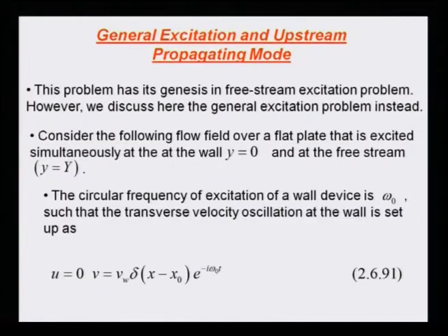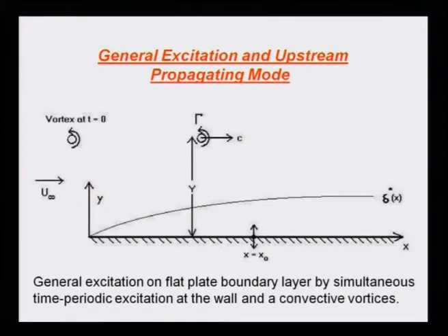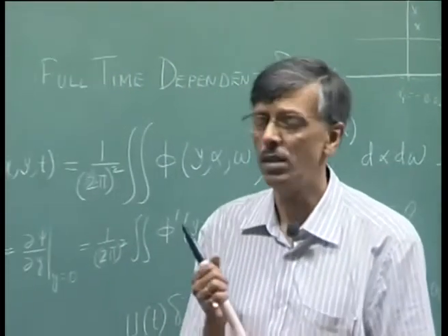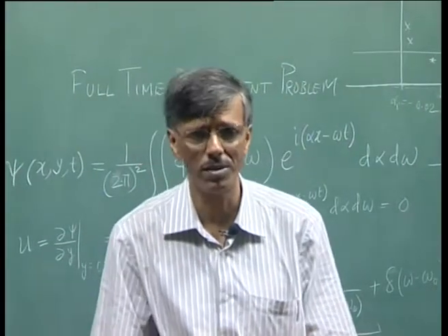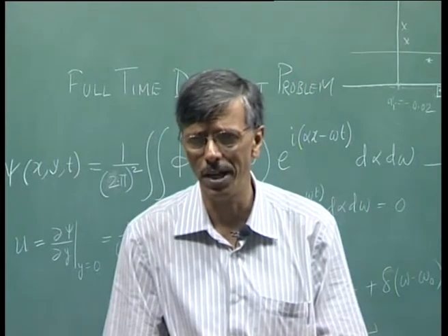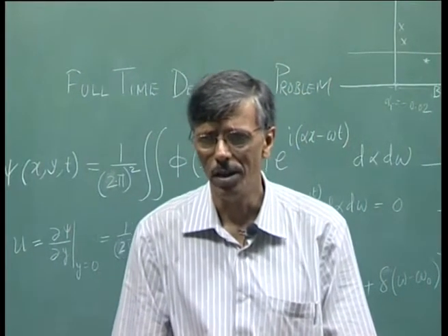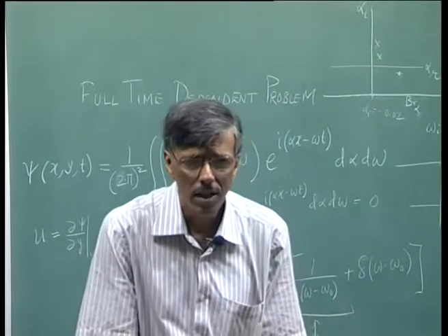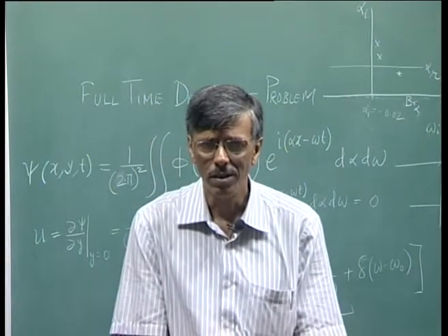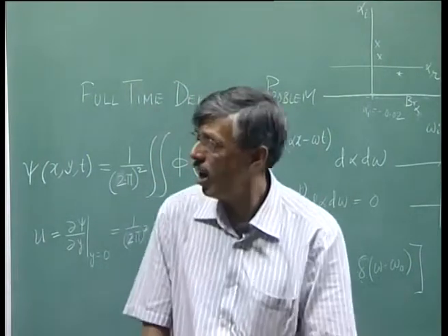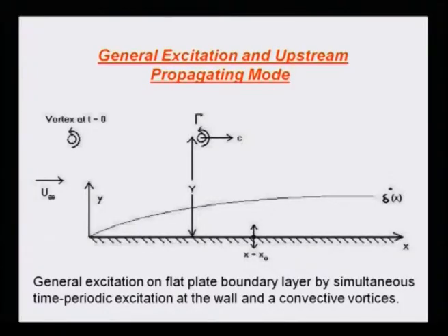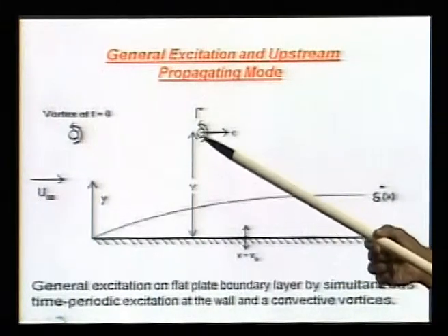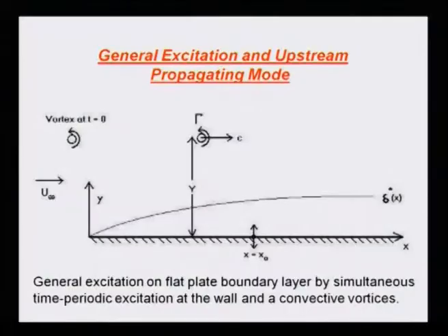So, that is the two wall conditions, that is what we had done. Now, what we are going to do is we are also going to provide a disturbance in the free stream. Now, you see what will happen. You recall that in our Orr-Sommerfeld equation we have 4 fundamental modes: 2 decay with y, 2 grow with y. But now in this general excitation case, what we need to do? Can we throw away those 2 modes which were growing with y? Because eventually I must match up to this disturbance level, I cannot just stay with the wall modes, because the wall modes decay. But if I give a finite disturbance here, I must keep those other 2 modes also alive.